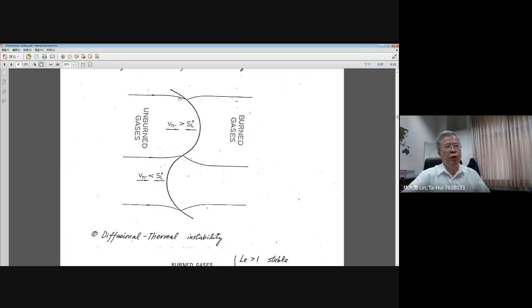then this curvature will give you the result to push your flame to move to the downstream, which means the curvature of your premixed flame will become larger, right? Larger curvature means the disturbance becomes stronger. Okay, this is the upper part. You understand that this is a small disturbance. Originally, you may have a small curvature, but it will continue to become larger and larger,